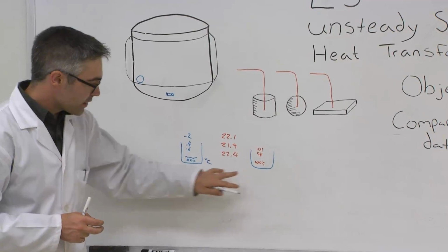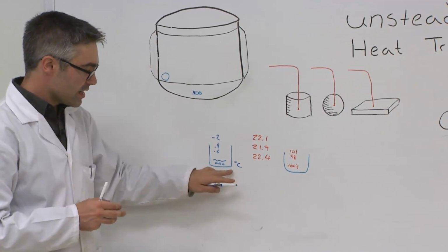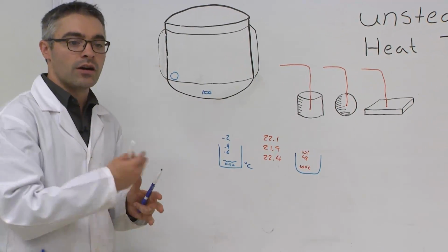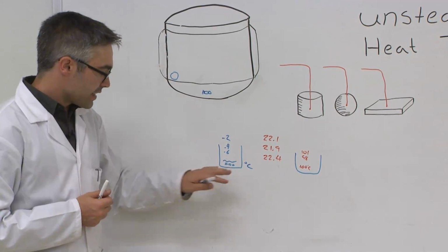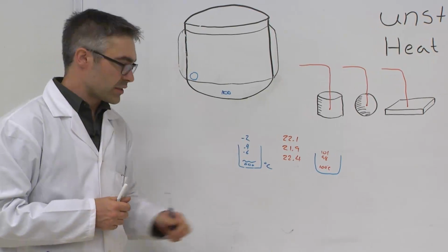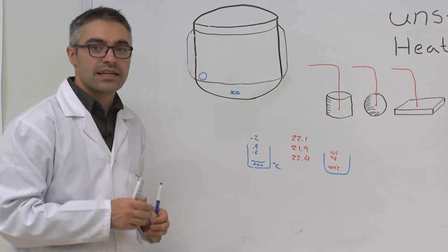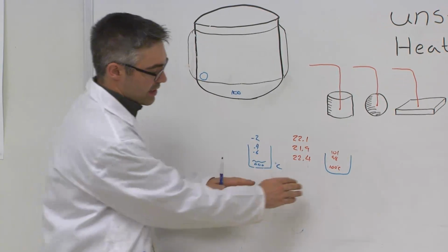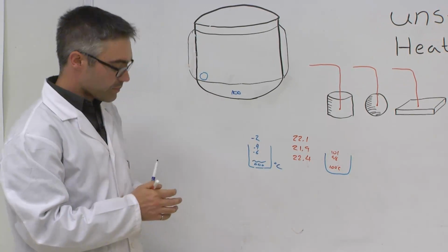We know that these are theoretical constants, as ice water will be 0 degrees until all of the ice is melted, unless there is any gradient within the system. Similarly, water at 100 degrees and 1 atmosphere will boil at 100 degrees Celsius. Therefore, we can use these 2 points to calibrate our thermocouple system.